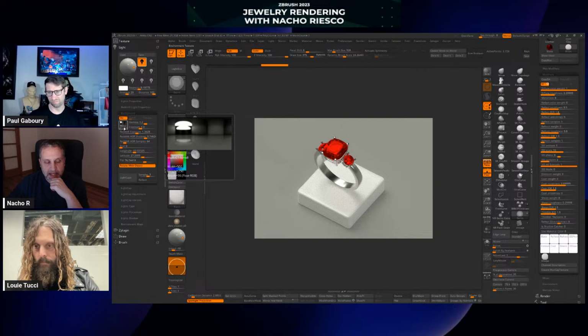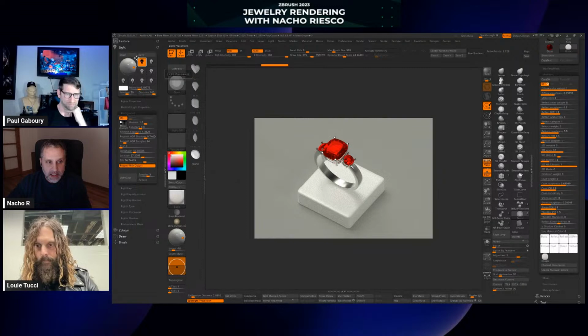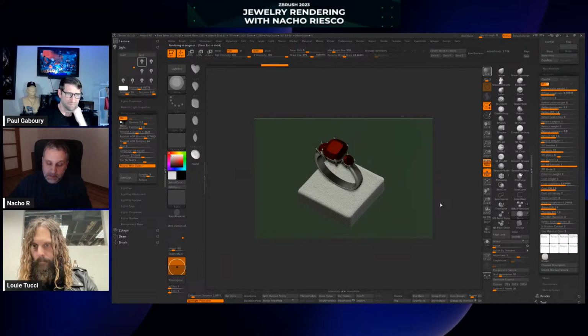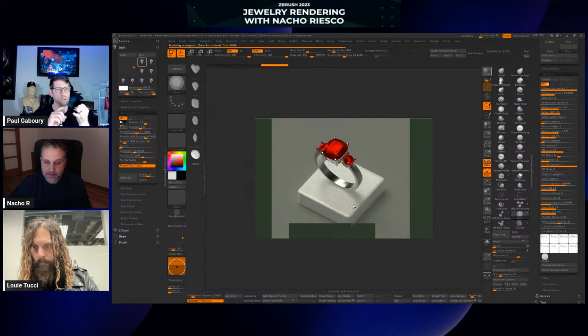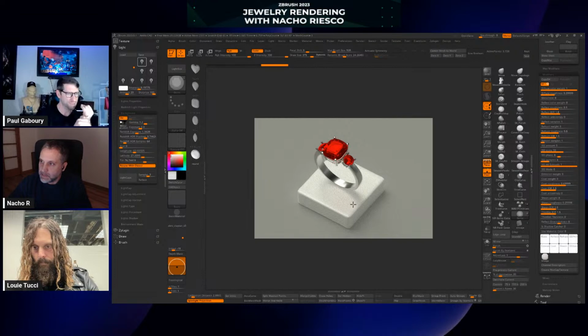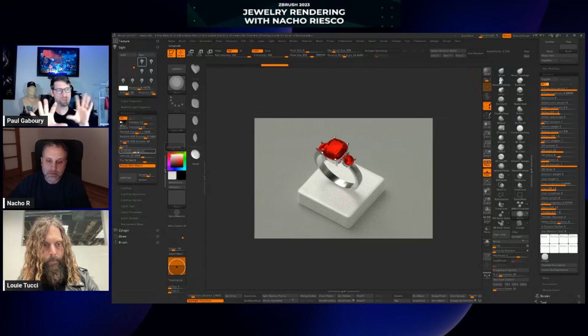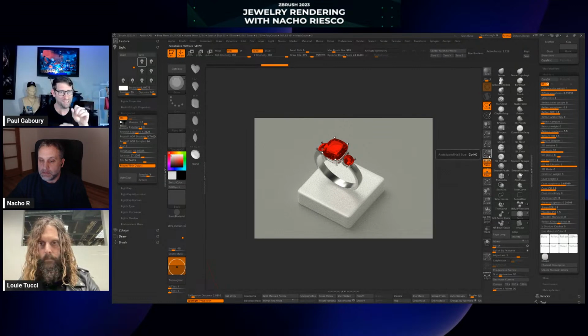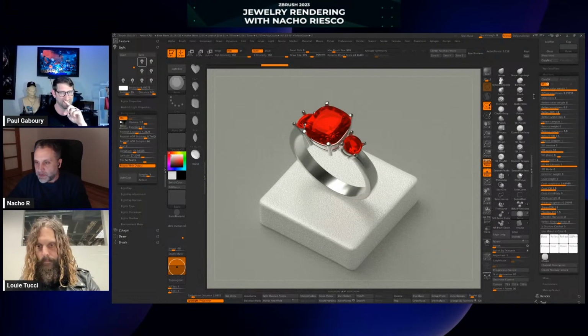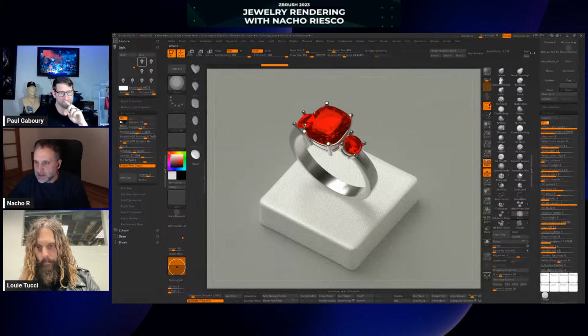The lighting comes from an HDRI environment, and I also have this light here. If I turn this off, you are having a different lighting on this scene. Yeah, so you pretty much use the defaults of the render settings. You use an HDR image. And it looks like you're taking advantage of the ability of having Redshift with ZBrush. It looks like you're using also the filter system at the end. You're using an Orton at the end, it looks like? Yes. For example, for this one, I already use, I think, as far as I remember.